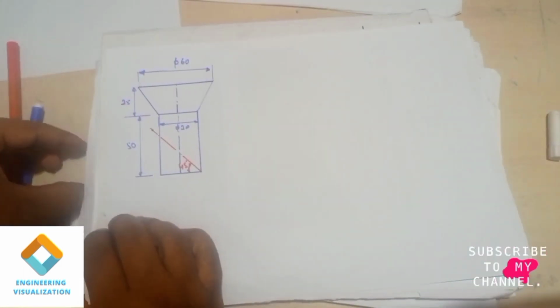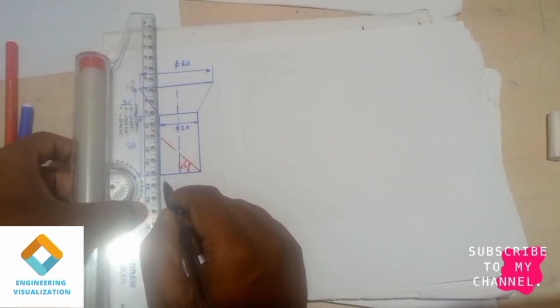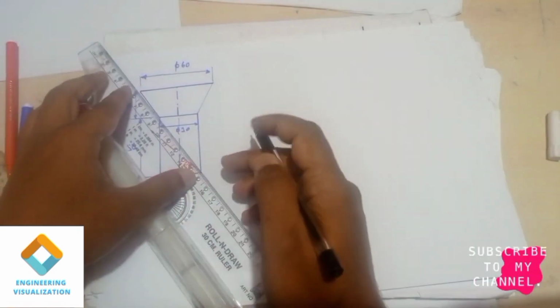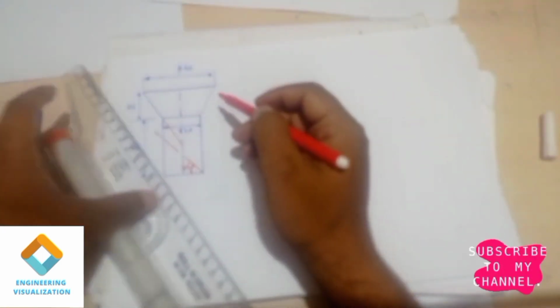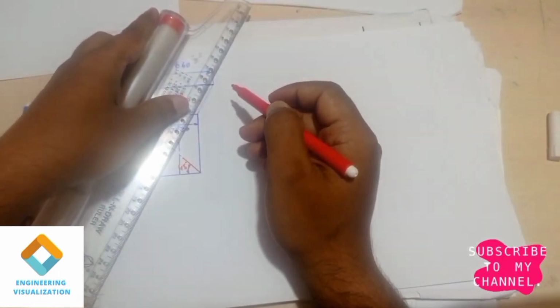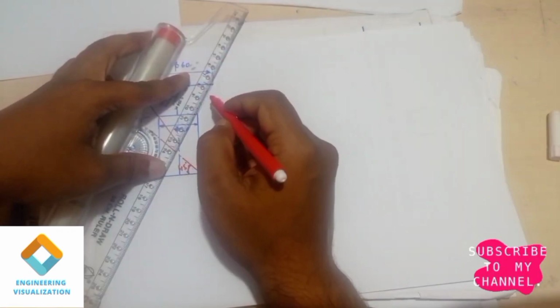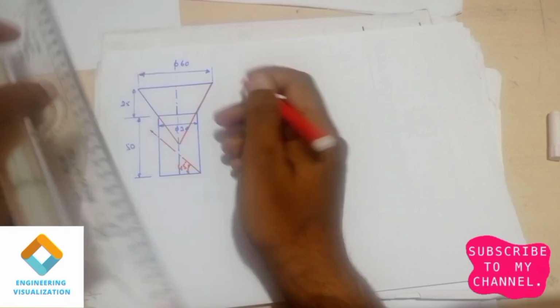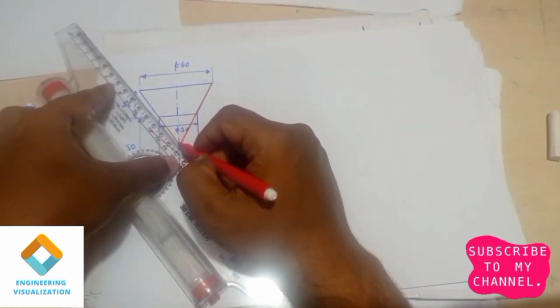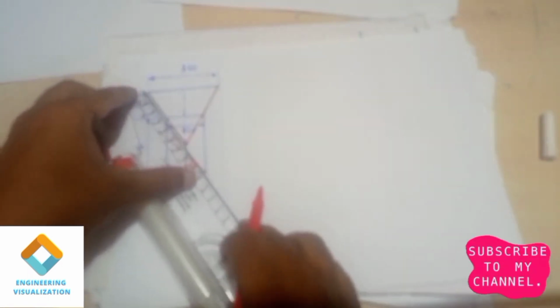Now we need to construct the top view of this cylinder, so that showing the cutting becomes very easy. For the upper part of the funnel, when we construct it this will not be possible, so we will extend it to make it look like a cone. The construction of the cone we know using the formula small r by capital R into 360 degrees. We can do that, so just extending that. The tapered part will be easy for us when we do the development of it. So I can measure this dimension, how much it is.